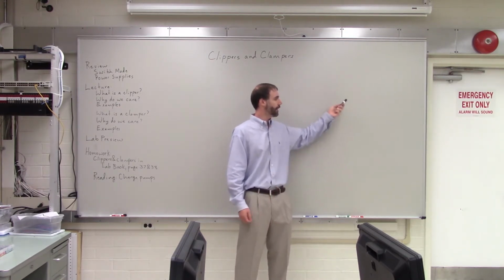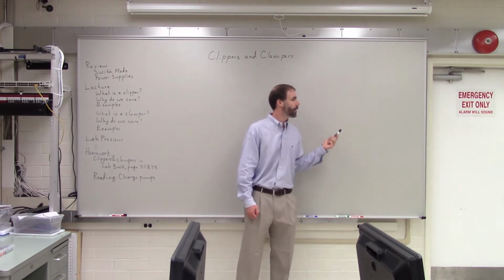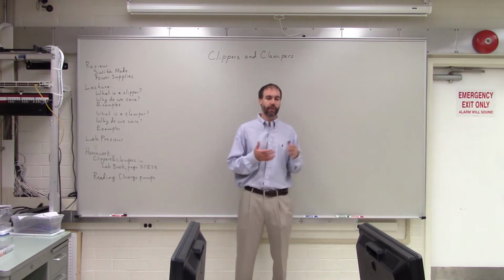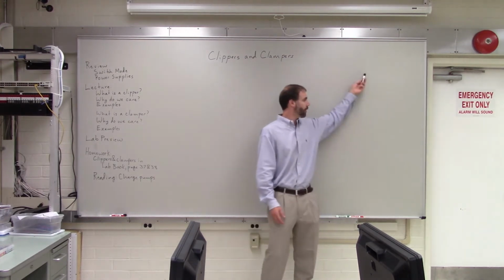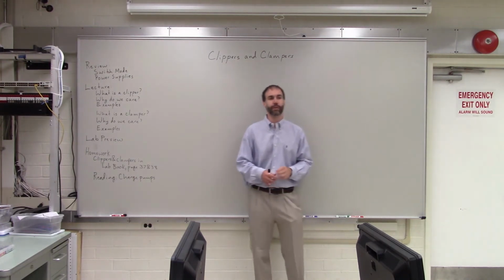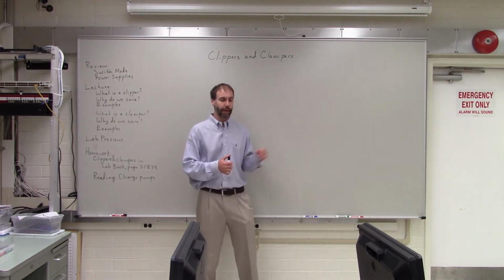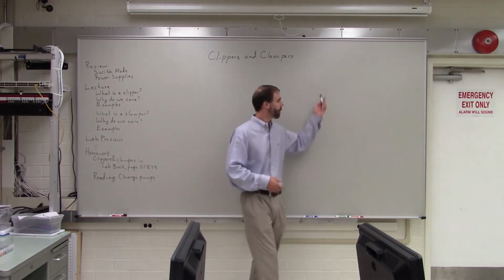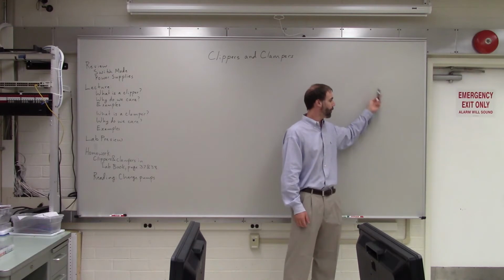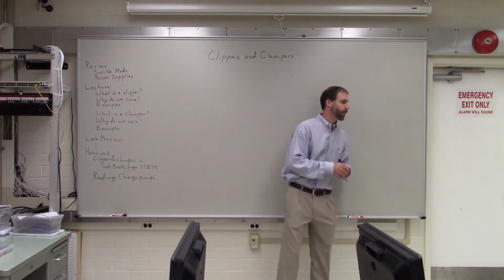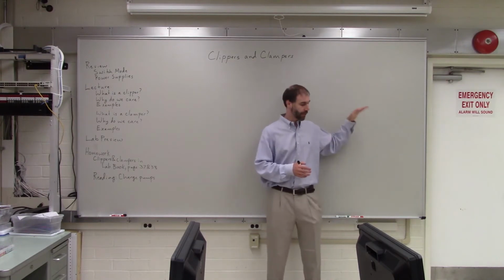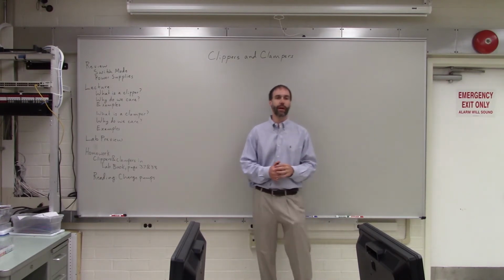And then they would feed that signal through a transformer. And then that transformer can increase the output voltage. And they could have several taps off of that transformer. So you could have several different voltages coming out of that transformer. And then those output voltages were filtered to smooth them out, and then that's how we got the DC output voltages.